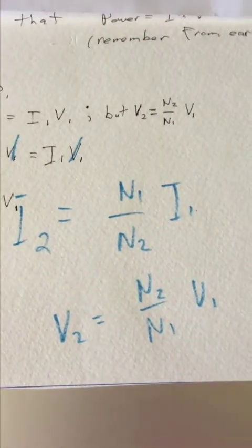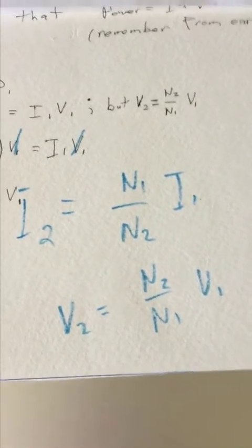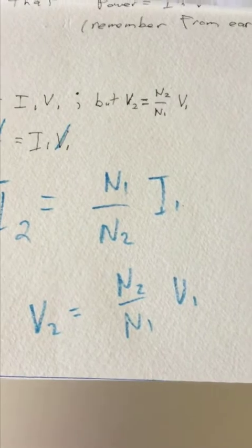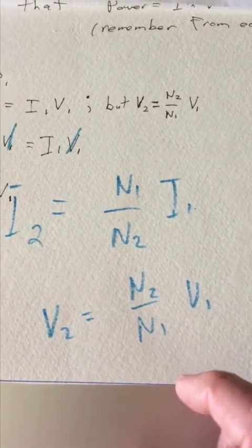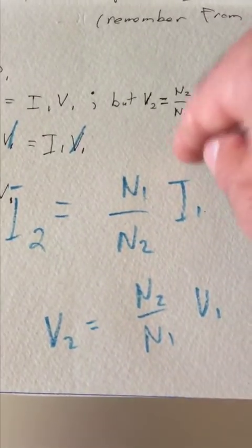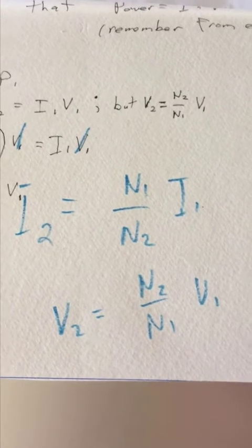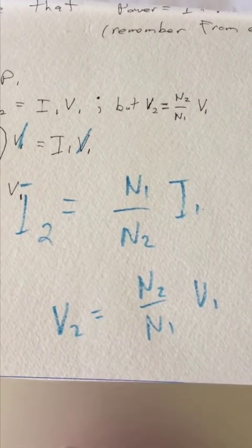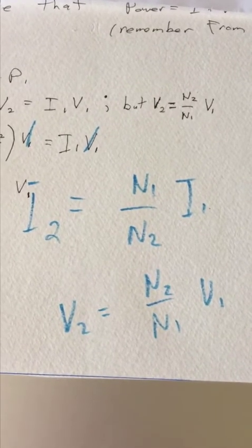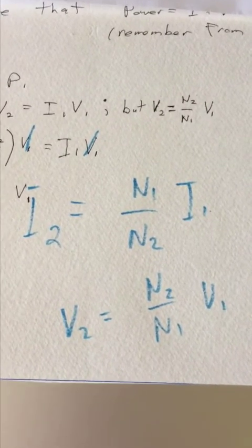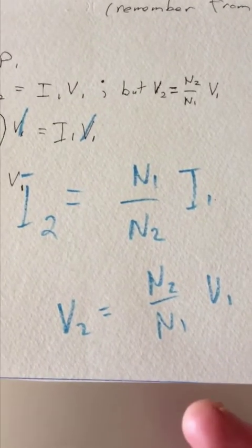So that's why in those really long distance transmission lines, where you get wires sending energy through hundreds of miles across the country, you're going to have really high voltages because you're stepping up the voltage, but you're stepping down the current. And that allows for less loss on the transmission lines, so you need transformers from the point where the power supplies, the turbines and all that, are providing energy to the grid. There's transformers to make that energy be at high voltage and a really low current.